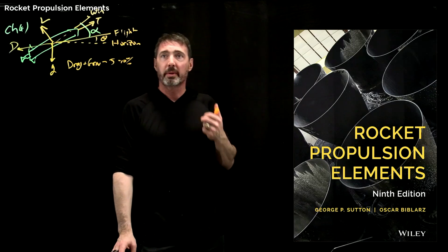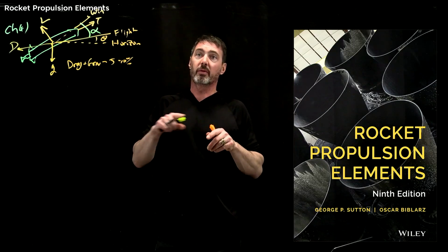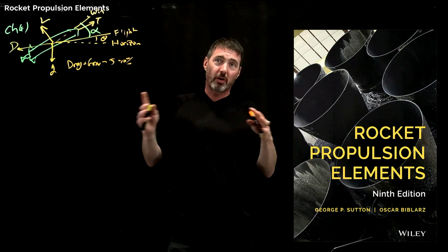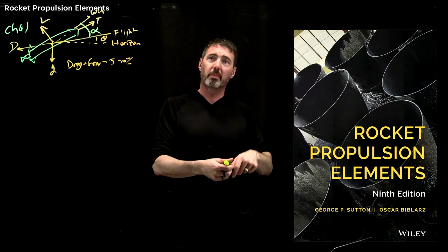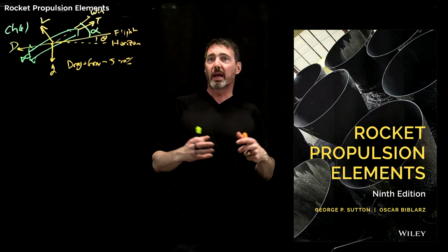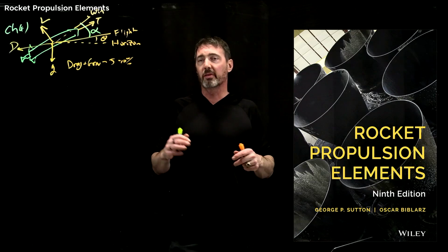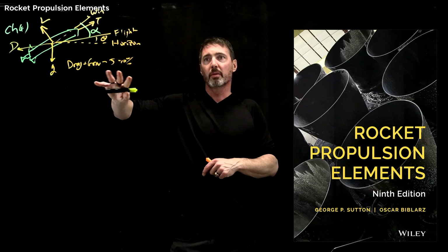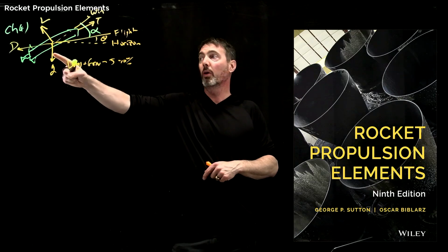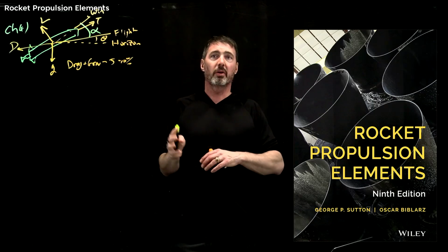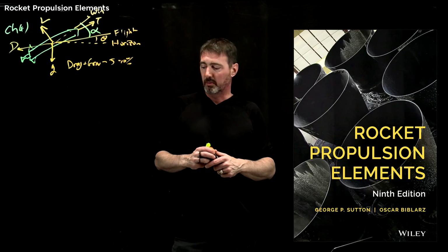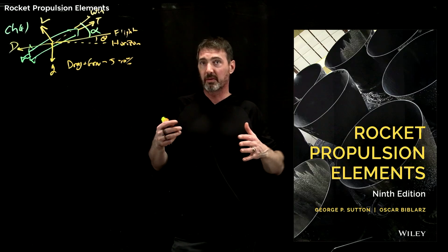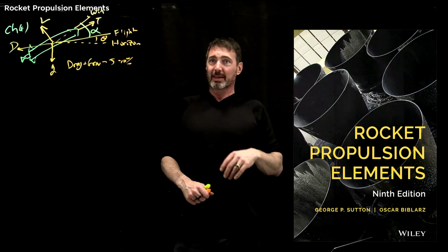Now at Virgin Orbit, we were dropping a rocket off the wing of a 747, and so it was actually harder aerodynamics. We had to drop it, count to 5, start the engines, and the rocket would pull up. There was a big pull-up maneuver. We had to have a little bit bigger flight surfaces. So the point is, it was not easy, and there are loads associated with this. These are the forces. There are also vibration loads and aeroacoustic loads that you've got to deal with. Rockets are not the strongest of things, so they can also banana.